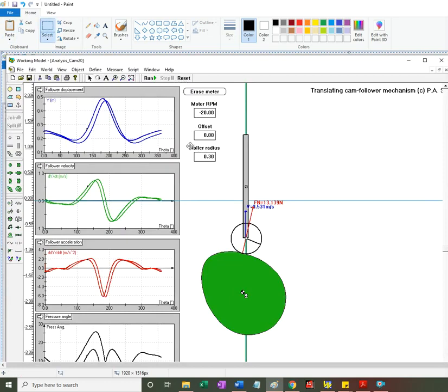and we have the case of our roller follower. We're going to look at the angle that is formed between the normal force at the contact point. Okay, so there's the contact point. It won't be the velocity of the contact, but rather the velocity of the center of the roller. So this is going to be the pressure angle gamma.